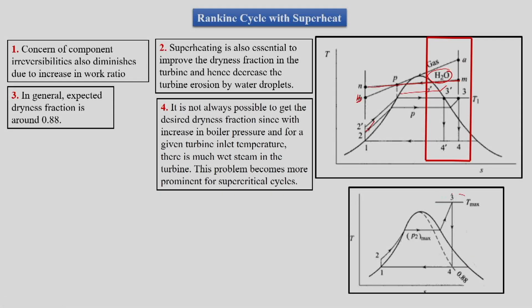So there is a freezing at this level due to metallurgical limits of the material which is getting used for boiler and turbine. Turbine has a problem that turbine rotates. So in the case of rotation, it undergoes compression and expansion as a cyclic phenomenon. So there is a fatigue involved in the turbine design.